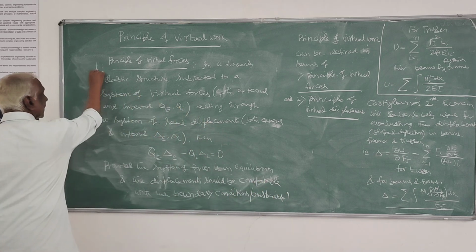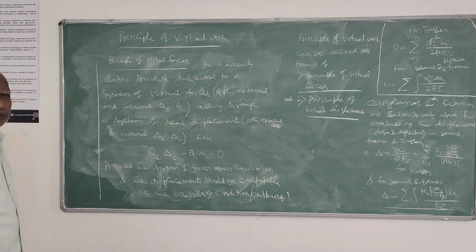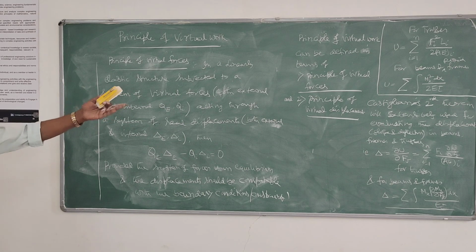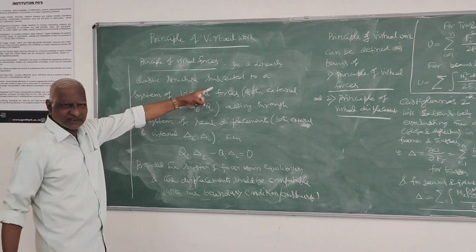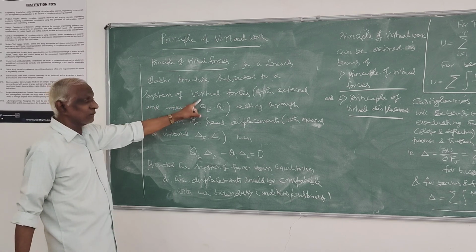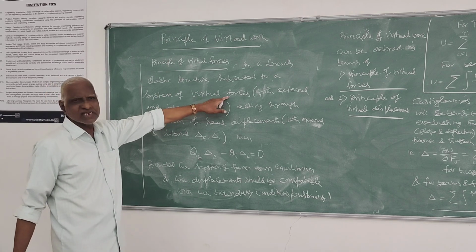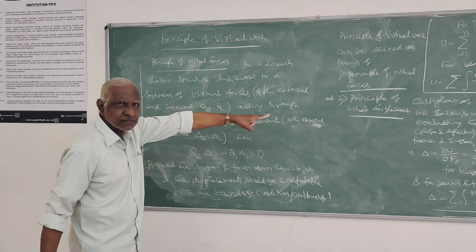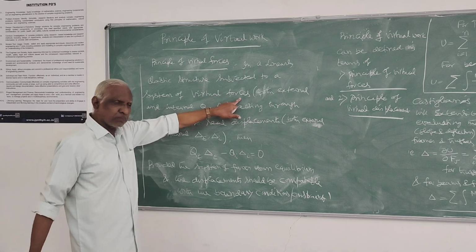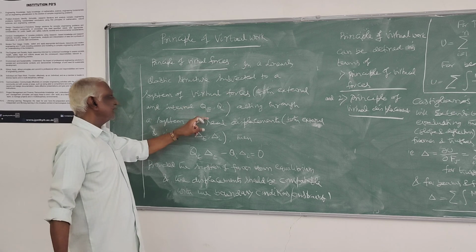So this is called the principle of virtual force. On similar lines, you can define the principle of virtual displacement. Same thing in a linearly elastic structure subjected to a system of virtual displacements. Here it was virtual force; there it corresponds to displacement. Virtual displacements, both external and internal.